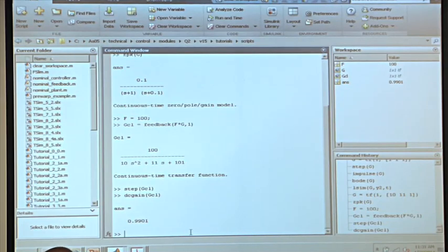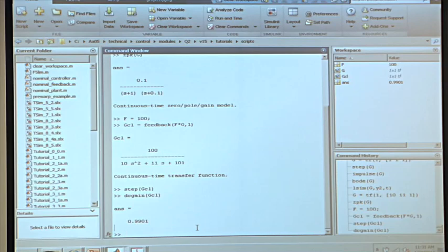Okay, that's great. Now we need to know something about the phase margin, because we're tuning this compensator to achieve a phase margin of 45 degrees at 3 radians per second. That's the target specification. There's a nice script called margin, and we apply this to the open loop, the open loop that Nyquist used when he did his mapping. So margin f times g.